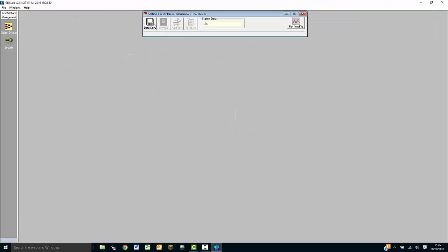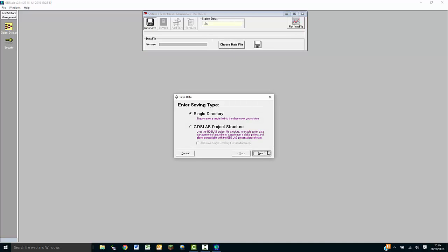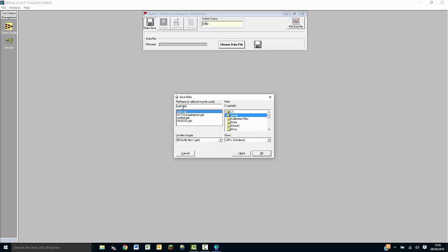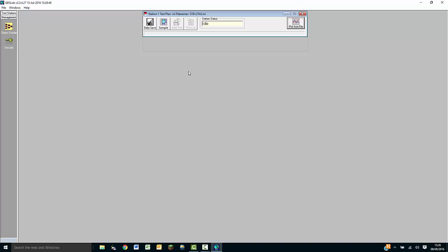Because we have frame displacement now, we're going to be able to control it, because it's actually quite a special feature, I would say, because essentially this is a standard triaxial setup, which could be with any velocity controlled load frame from any manufacturer. So a very, very basic staple piece of equipment that most laboratories have, that they only ever use by walking up to it, pressing start at a particular velocity, and maybe taking the details down on a clipboard.